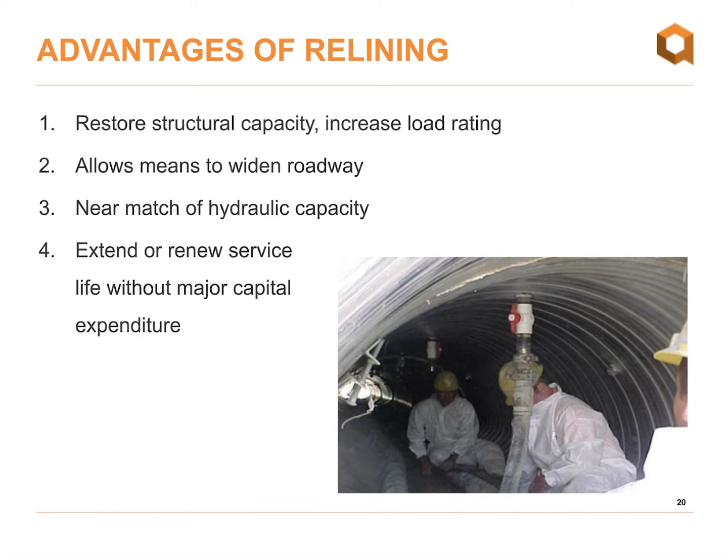So I talked about reducing the end area. So this is kind of on a case-by-case basis, and it depends what we're relining the structure with. But we do have smooth wall liners as well, which can help increase the efficiency of the culvert and reduce losses throughout the length of the system. So with that, we can oftentimes nearly match the capacity on a hydraulic level.